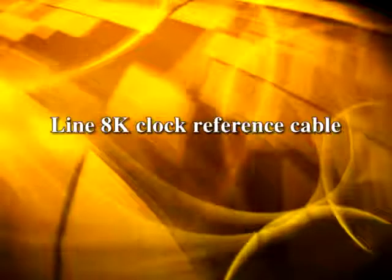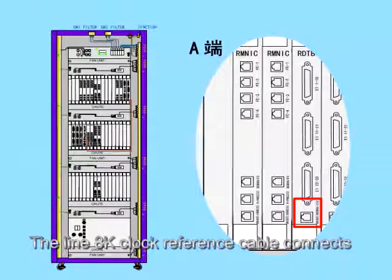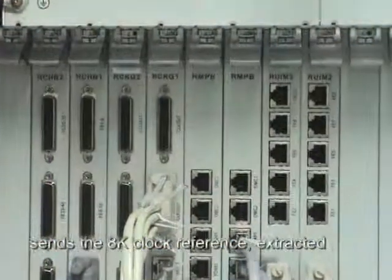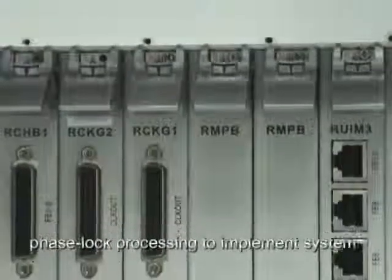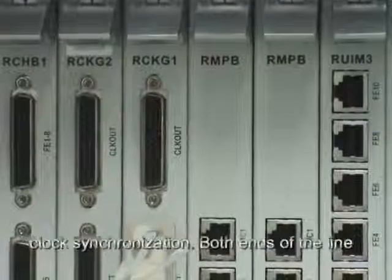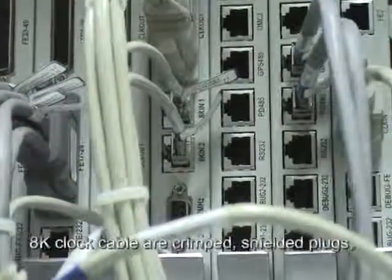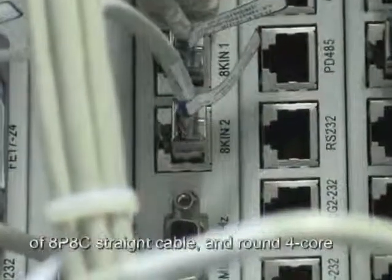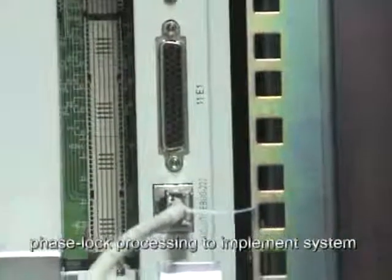Line 8K clock reference cable. The Line 8K clock reference cable connects the line clock and the CLKG board and sends the 8K clock reference extracted from the line to the clock board for phase lock processing to implement system clock synchronization. Both ends of the Line 8K clock cable are crimped shielded plugs for 8P8C straight cables. Round 4-core single-strand cables are adopted.